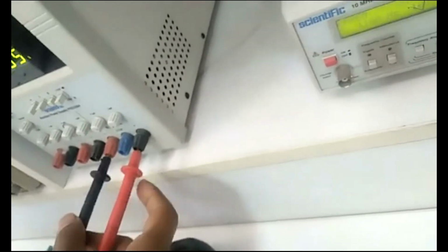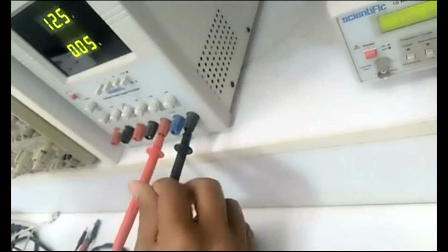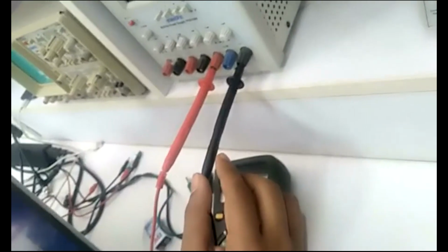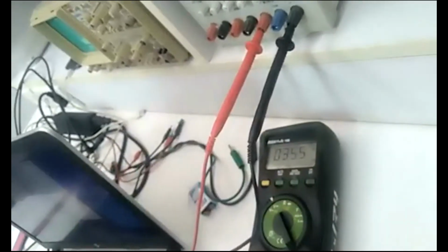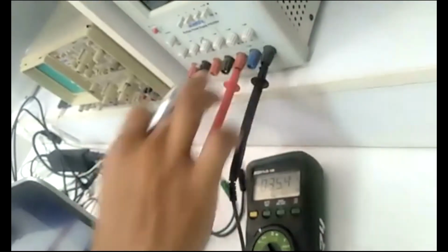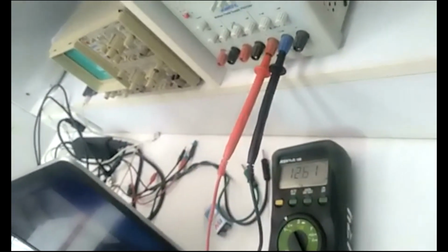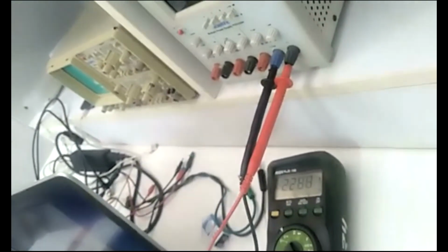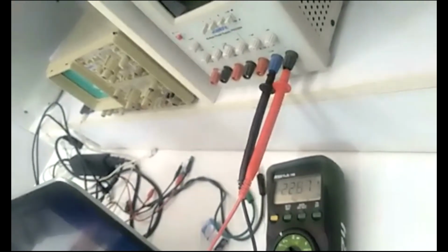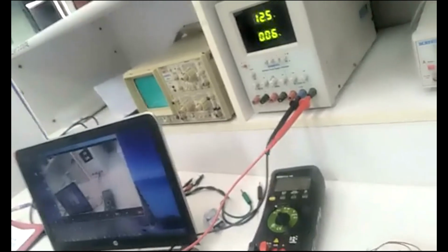Then let's check the voltage between these two. Okay, so the total voltage between these two terminals is 35 volt, and with respect to the common it is plus 12 volt. That is why with respect to the common, the negative one is showing minus 23 volt. So this is the use of the common source in a power supply. This is specifically a DC source, or DC power supply.